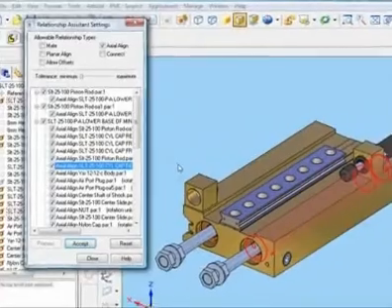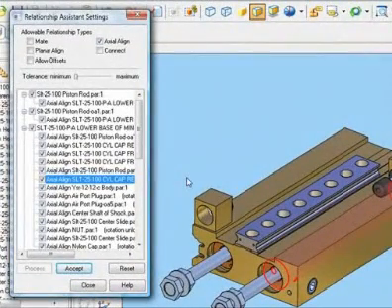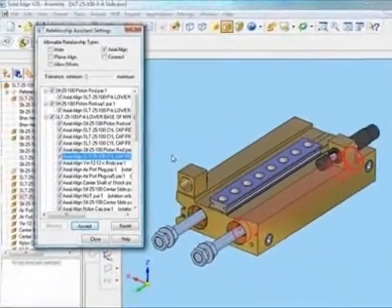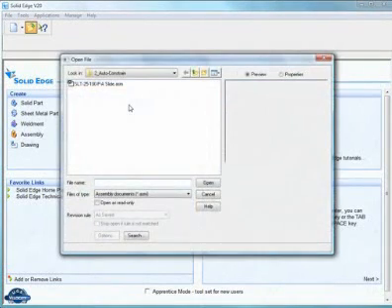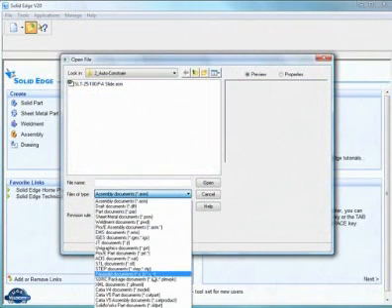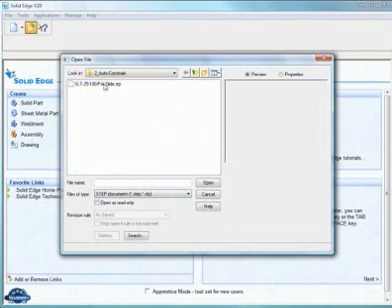Solid Edge's auto-constrain tools are able to add parametric assembly relationships to imported data, no matter which modeling system created it. Adding relationships to components in an assembly ensures they are accurately positioned relative to adjacent components, enables exploded assemblies, and allows them to take part in motion studies.